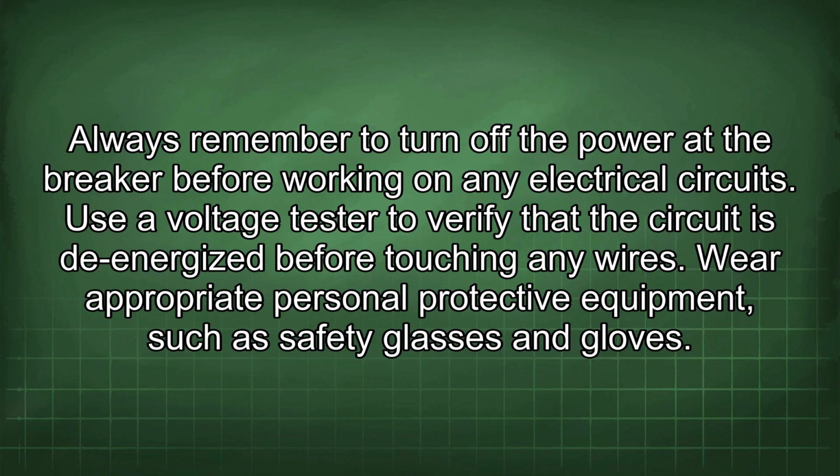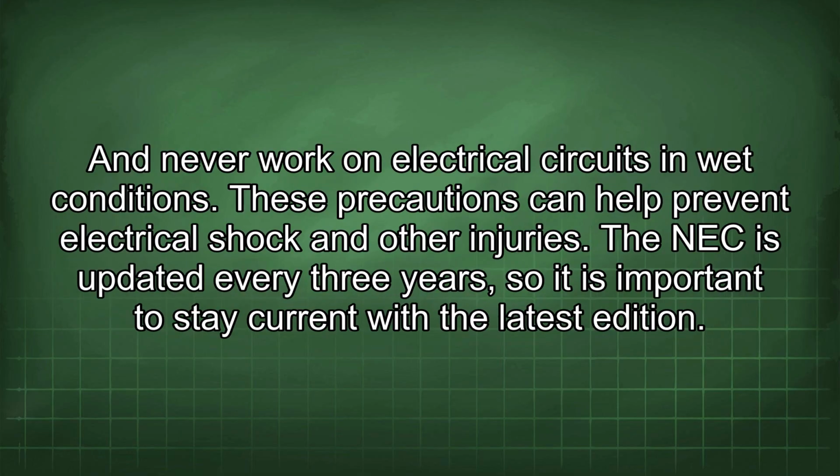Use a voltage tester to verify that the circuit is de-energized before touching any wires. Wear appropriate personal protective equipment, such as safety glasses and gloves. And never work on electrical circuits in wet conditions. These precautions can help prevent electrical shock and other injuries.